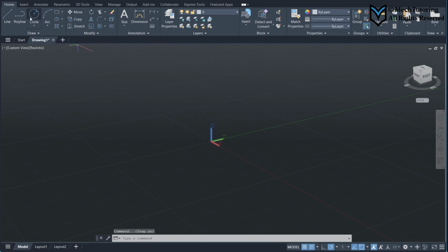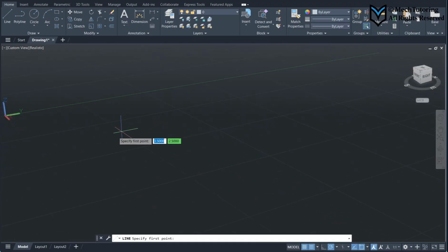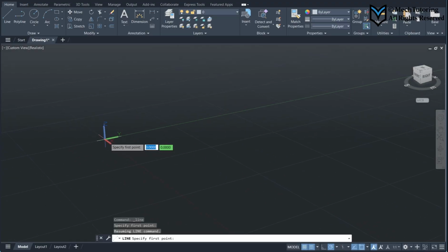That will make sure that when you draw anything, your mouse will only move between the grid points. It will not stay anywhere in between that, okay? For example, look, there are 5 divisions of this dimension over here, so it's only moving on those grid points. So if you turn it on, it will help you snap properly onto the points where you want to snap.